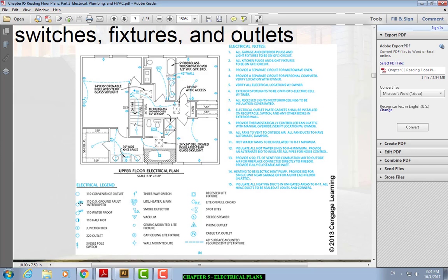You have seen them. I'm sure you go home and you go to the kitchen or the restrooms or outside, and those type of outlets, they're GFI, and you'll see visually the difference. And of course, you're gonna read on it in the book. Waterproof, of course, you want to put those back and on the outside, and those are capped, so water won't go in there. So for every electrical plan, you're gonna have symbols, and with a symbol on the legend, it tells you an explanation of what it is. So when you start laying it out and putting those light fixtures and outlets, whoever's reading that, they'll know exactly what you're talking about. Okay, but you have to provide the legend.